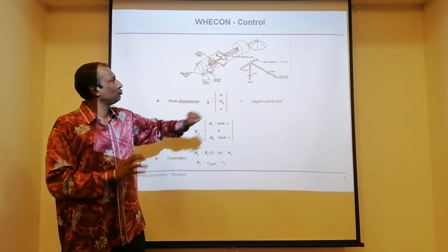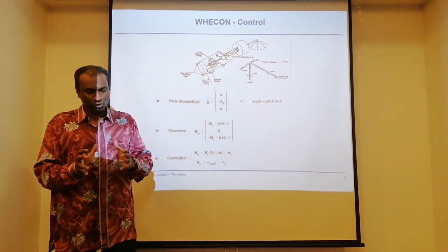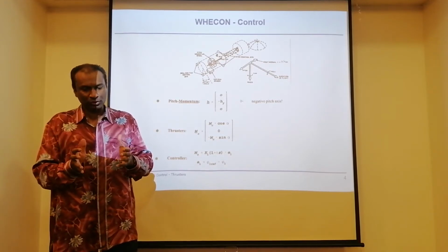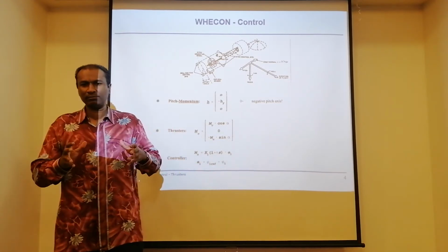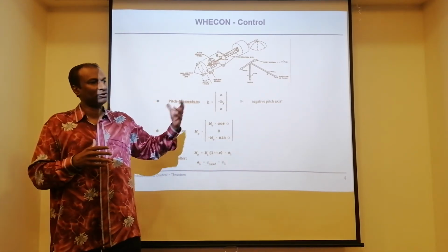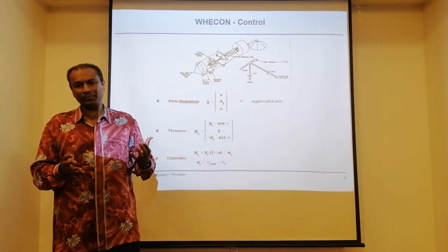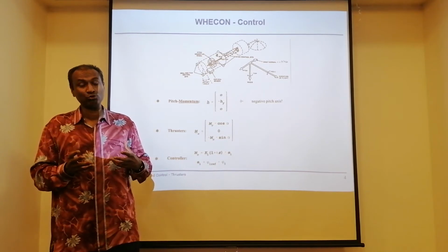So remember, I told you when you have a momentum wheel and you want to use it for attitude control also, what exactly happens? The speed builds up. So when the speed builds up, you need to dump the wheel. That we have learned. In the last chapter we used magnetotorquers, but you can also use the thrusters to dump the wheel.